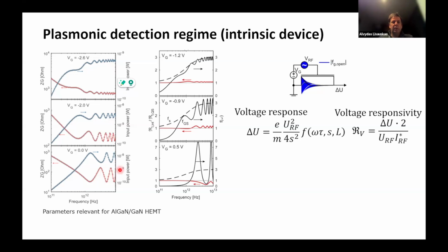Now, if one looks into what input power one has to apply, so this product here, one would see, oh, but actually the input power would also vary. And it varies in the opposite sign. You would like to get that enhancement away. With enhancement here, the impedance gets lower, so you have to apply higher power. When the impedance gets higher, you have to apply lower power here just to create the change, or it just gets less power.